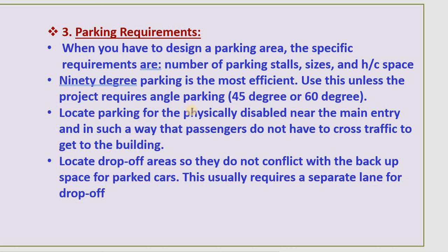We need to locate parking for the physically disabled near the main entry, and in such a way that the passengers do not have to cross the traffic to get to the building. Locate the drop-off area so it does not conflict with the backup space for the parked cars. This usually requires a separate lane for the drop-off. If we design a drop-off, you need to place it as far as possible from the parking space, because if you have parking spaces over there and the drop-off here, it is so dangerous for the people stopping and working on the car.